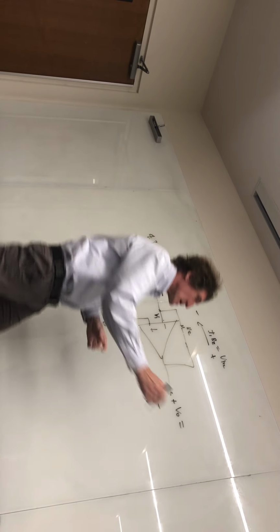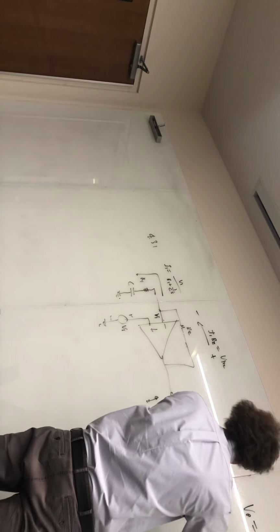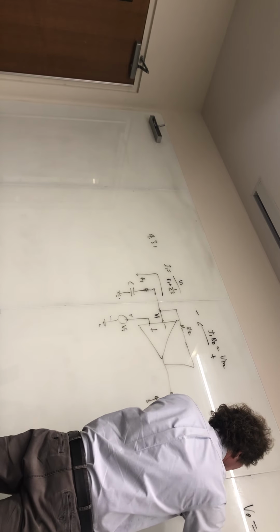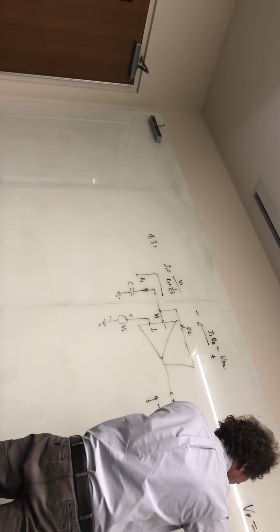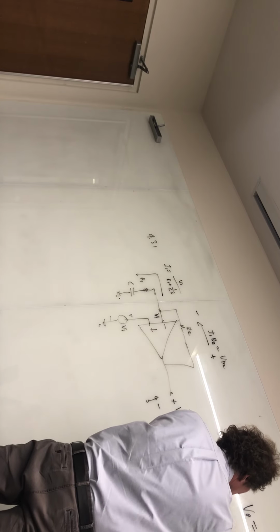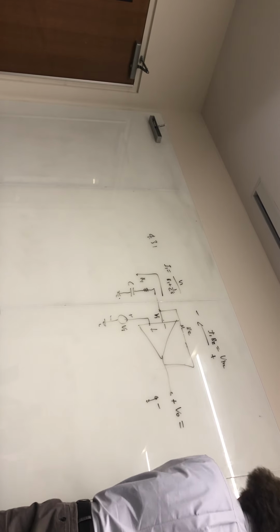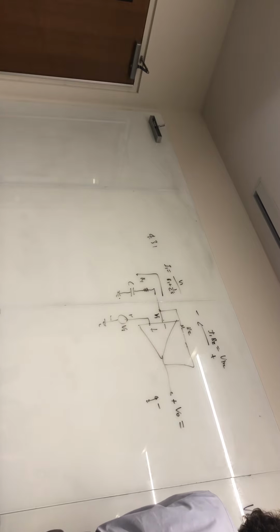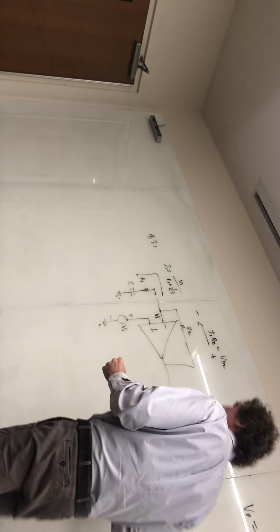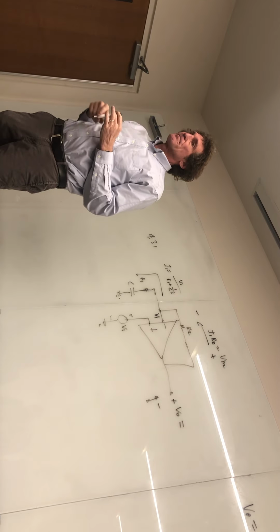All right, so I'm just going to say up here that V out is equal to I1, which is V in over R1 plus 1 over CS, times R2 plus R1 plus 1 over CS. There are obvious cancellations coming, but I wanted to make sure you saw the entirety of it. Do you all agree with me, class?